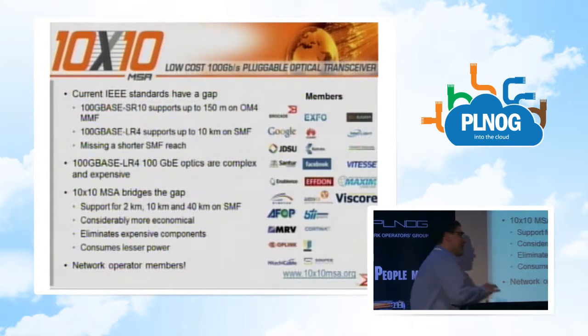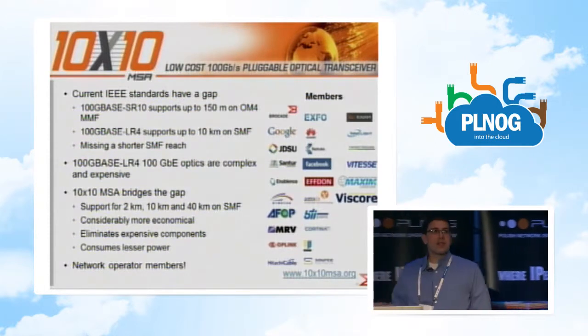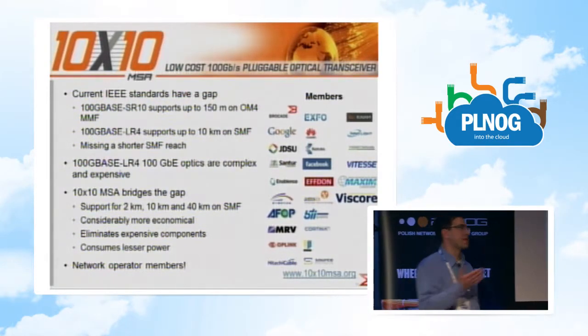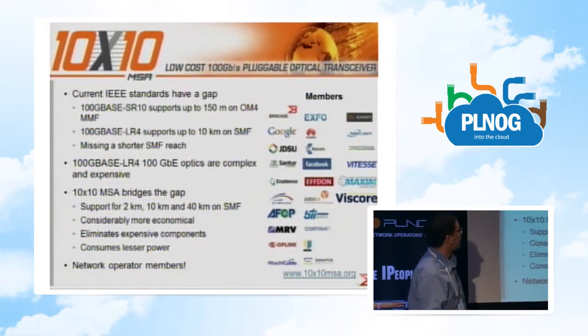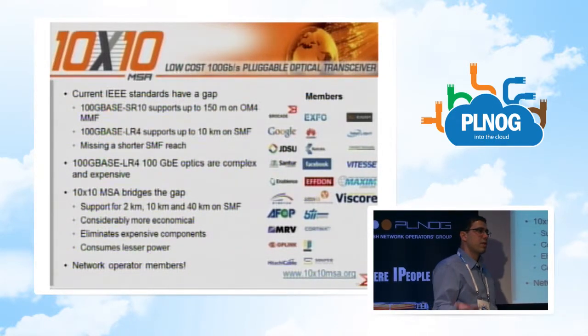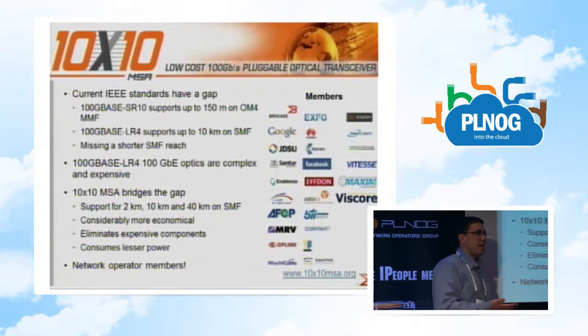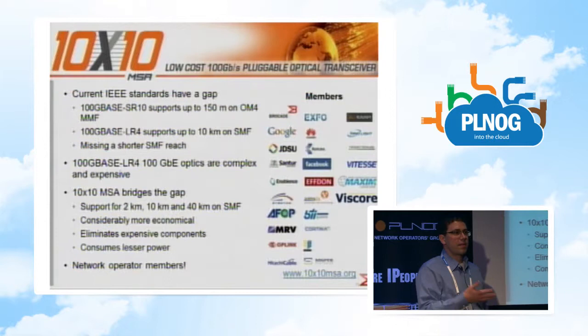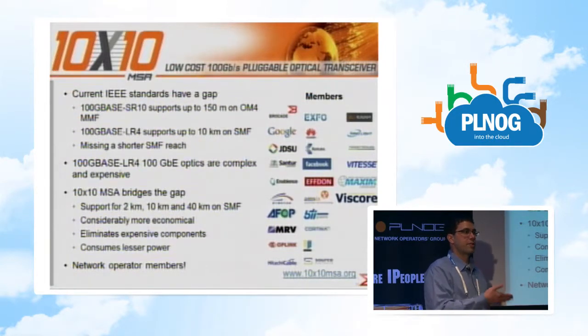So the good news is that you have more choice. Both of these modules in a sense are interoperable, because it doesn't matter if you have an IEEE 100GBASE module or a 10x10 MSA module. They're both going to plug into the same slot. They're both the same modules. They both use the same electrical interface.